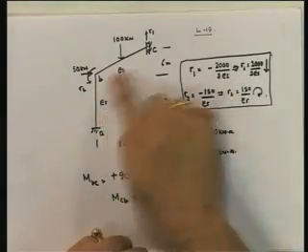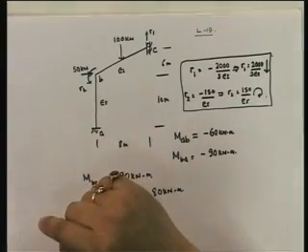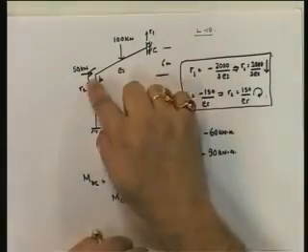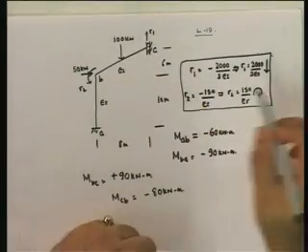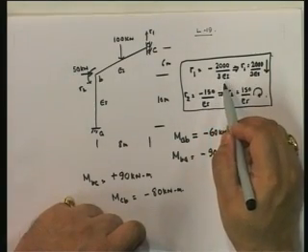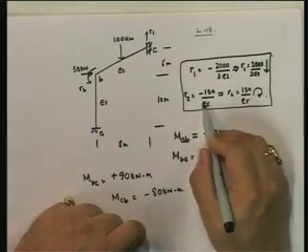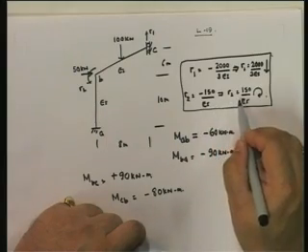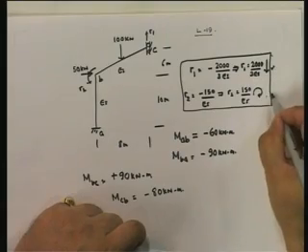Remember that this was the ABC frame with a 100 kilonewton load here, 50 kilonewton load here. R1 and R2 were the two degrees of freedom, displacements corresponding to the degrees of freedom. When we solved for R1 and R2, we got R1 equal to minus 2000 by 3 EI, which essentially means R1 is 2000 upon 3 EI downwards. R2 was minus 150 upon EI, which essentially means R2 is 150 clockwise. I hope you've got these answers too. If you have, pat yourself on the back, because you have understood the displacement method reasonably well.